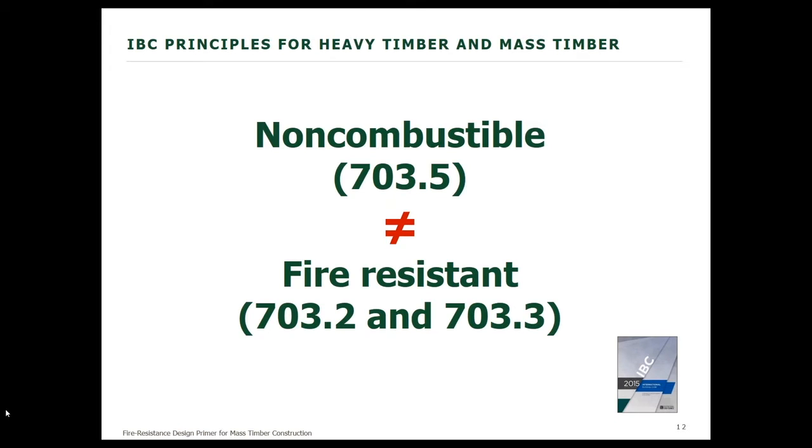Conversely, you can have a combustible building element, such as a heavy timber or heavier mass timber wood beam, wood frame wall that has high fire resistance. This is because of the inherent fire resistance of the timber, which retains its strength even while burning, or the fire resistance of the non-combustible covering of the wood structural elements, or both. It can perform its function for a long time in fire conditions.